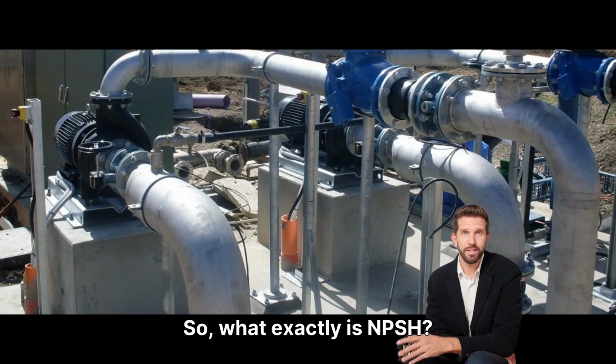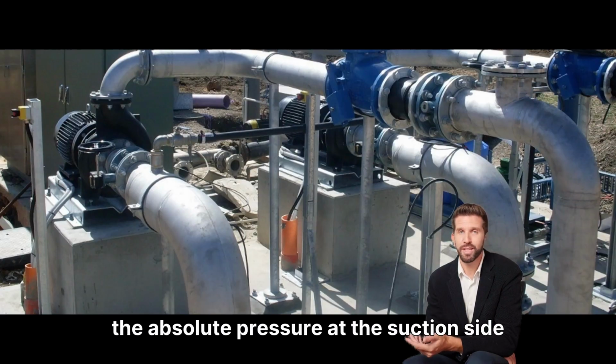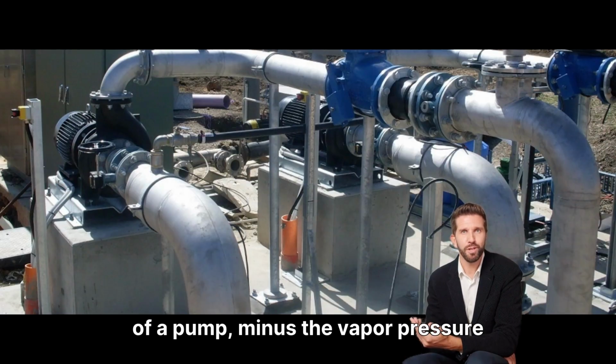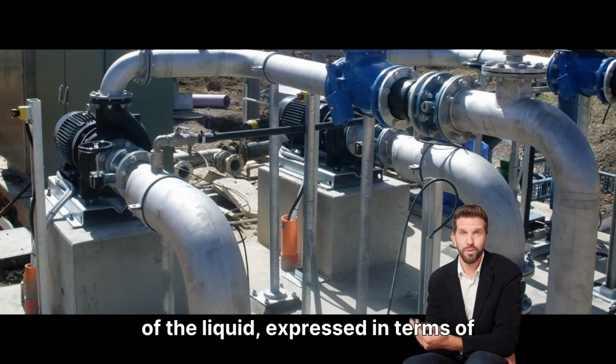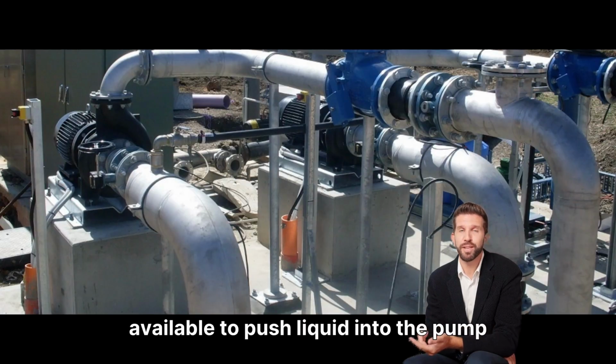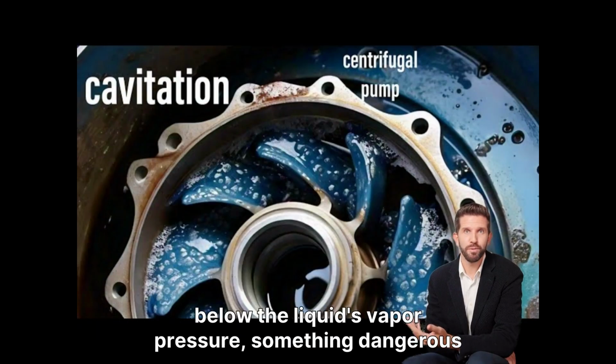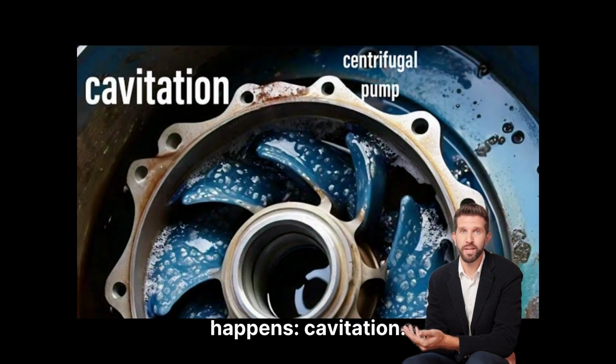So what exactly is NPSH? Simply put, net positive suction head is the absolute pressure at the suction side of a pump minus the vapor pressure of the liquid, expressed in terms of head. It's a measure of the pressure energy available to push liquid into the pump impeller. When this pressure drops too low, especially below the liquid's vapor pressure, something dangerous happens: cavitation.